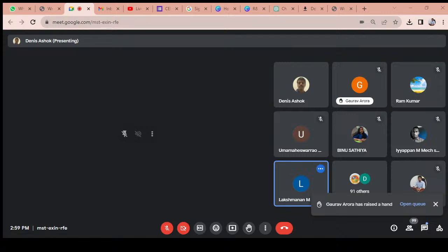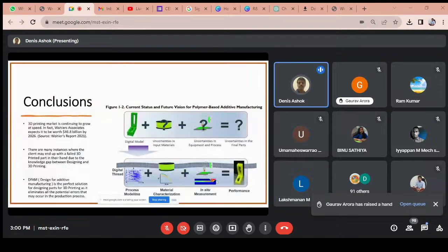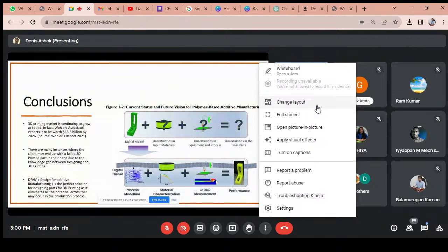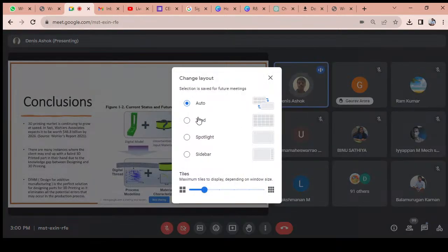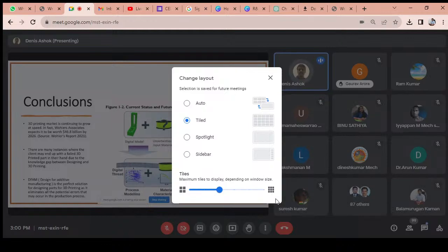Is there any facility for testing in metal additive fabrication at VIT? Sir, we have an X-ray tomography system. After printing, we can go for non-destructive evaluation of these structures, for any internal cracks which might have been formed by this layer-by-layer process, because the top layer will be hot while the bottom layer will be cold, so there can be some residual stresses, and because of that there will be some cracks at the joints.